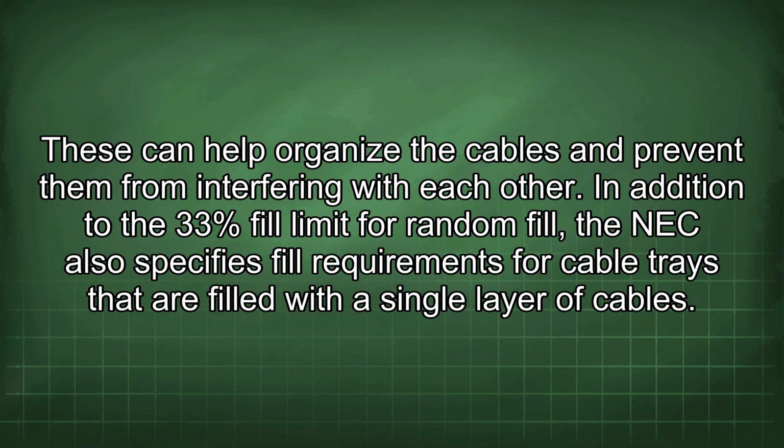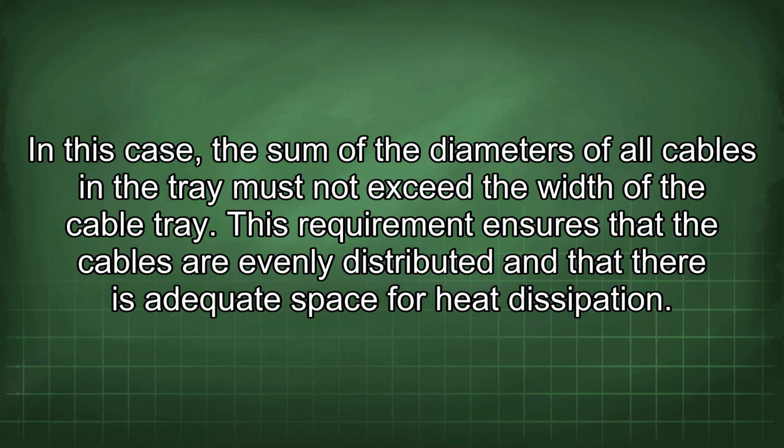In addition to the 33% fill limit for random fill, the NEC also specifies fill requirements for cable trays that are filled with a single layer of cables. In this case, the sum of the diameters of all cables in the tray must not exceed the width of the cable tray. This requirement ensures that the cables are evenly distributed and that there is adequate space for heat dissipation.